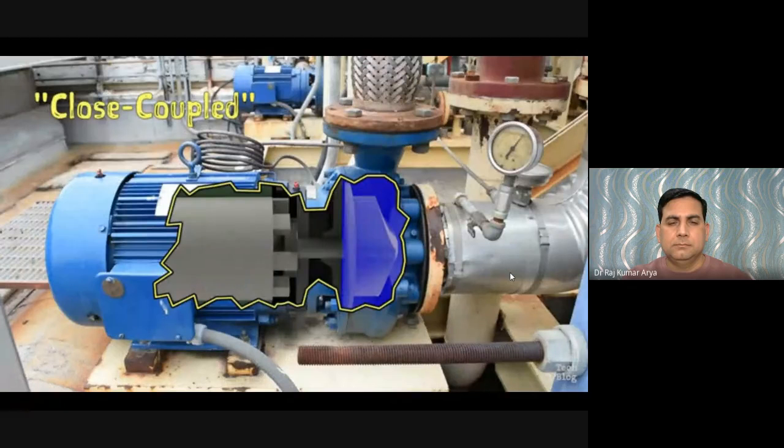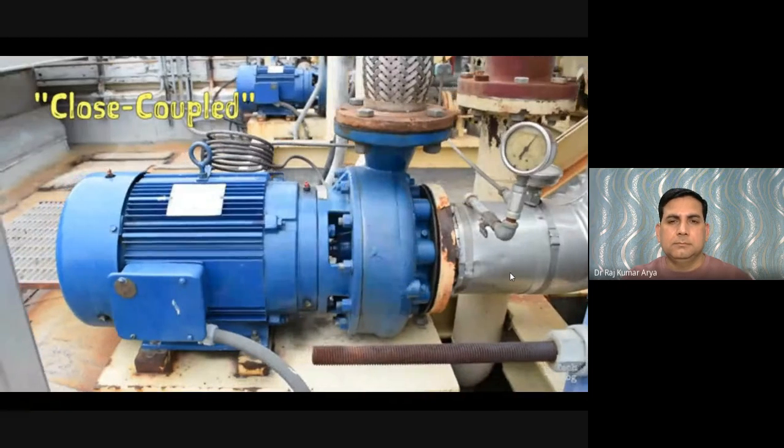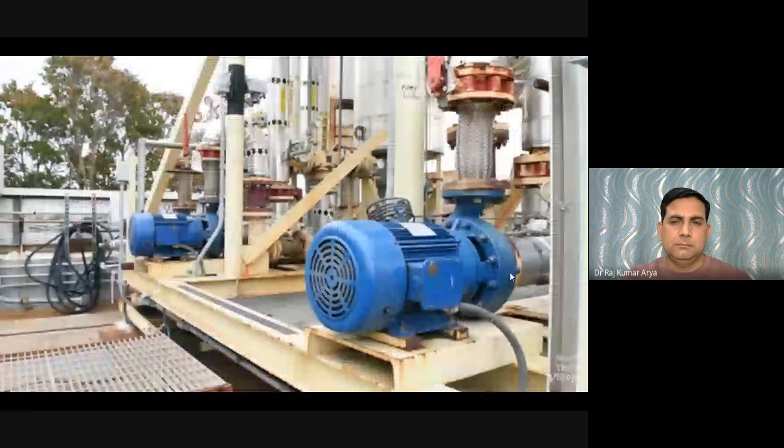In this case, there is no need for a coupling or any of the extra labor required to perform sensitive alignment procedures. However, since both the pump components and the driver components are supported on the same shaft just by the bearings in the driver, this mounting method is really only appropriate for small and medium-sized end suction pumps.